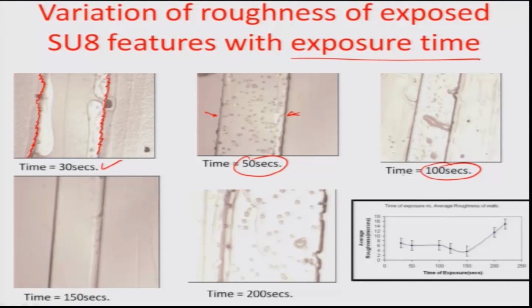Again, even sharper, and then probably the best edges come off here, beyond which you can see that because the exposure time is more now, the protons are diffusing out of the region which have been exposed, and there is always a rough edge because of this.